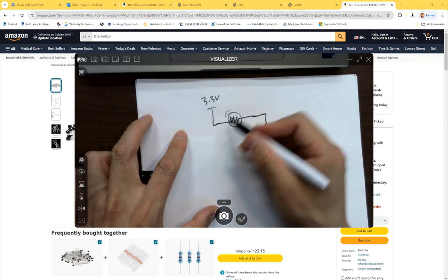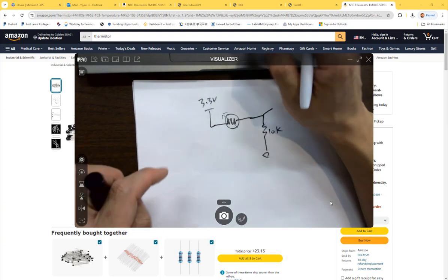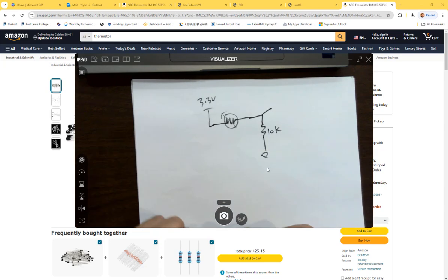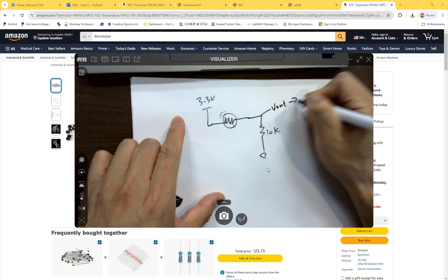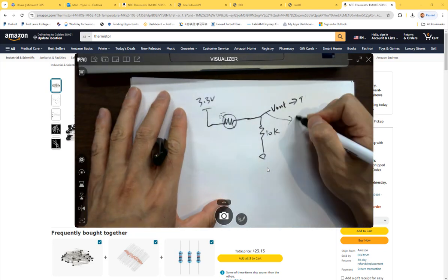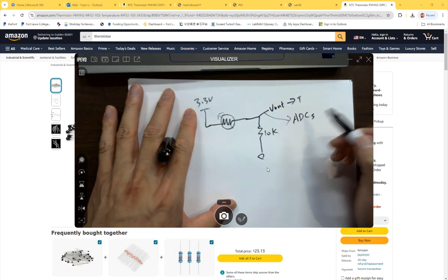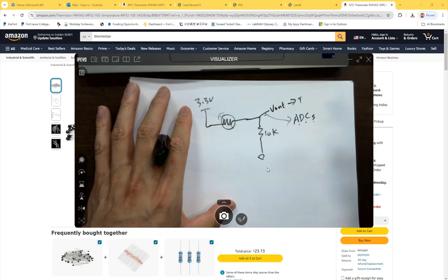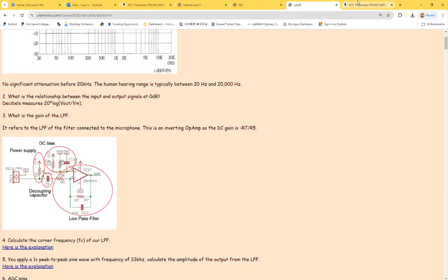Okay. So it's a voltage divider, so the analog voltage here will change depending on the temperature. And there's a certain equation that I can use to convert that voltage into a temperature. Okay? So that voltage can be digitized by what? Something we're going to cover today. ADCs, right? So analog to digital converters. So digitize this analog voltage and use a certain equation to convert it to temperature. Let me show the equation here.